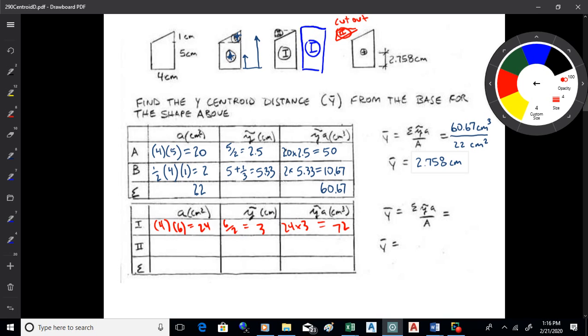How about the triangle? What's the deal with that? Very importantly, it's got to be negative because it's a cutout. It's the same area as the other one, but negative. So we get 24 minus 2. This bottom row is going to be the same. It's 22. How about y bar? What do you get for y bar for that cutout triangle? It's 6 minus...